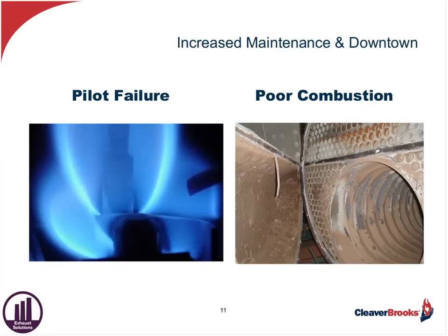Another problem that can lead to downtime is as you increase that pressure in the stack and breeching, you've got that pressure now being imposed upon the burner itself, we get into pilot problems. We also get into situations where we have flameouts if that restriction is large enough. So those are other problems that can lead to not just maintenance issues, but expensive downtime as well.